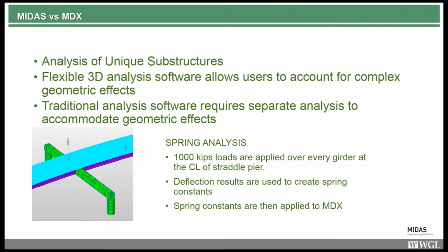And in the interior girder, we're actually seeing the exact opposite behavior, where MIDAS is seeing a little bit less negative moment than MDX. This is due mainly to the 3D load sharing capabilities that MIDAS is capable of, as opposed to just applying vertical springs to the model.